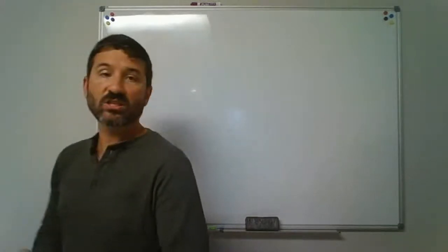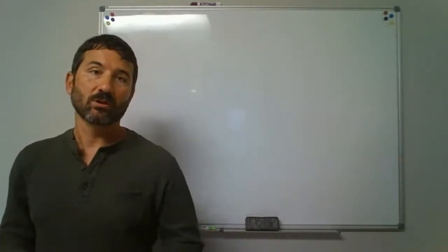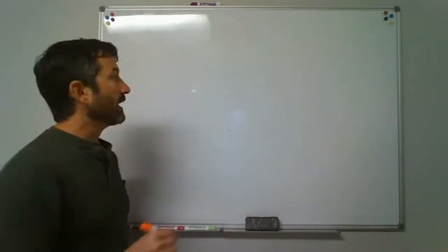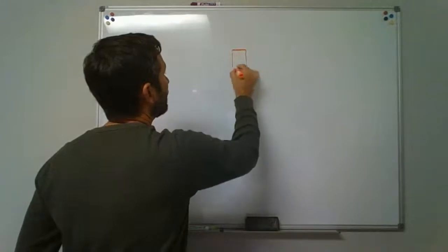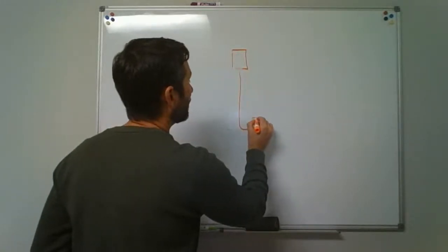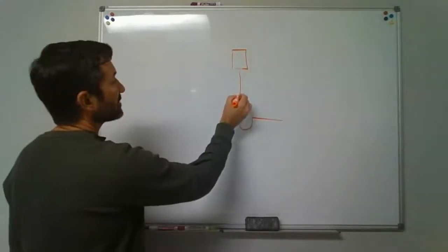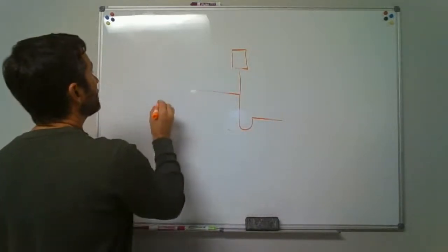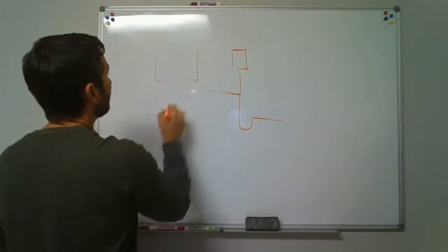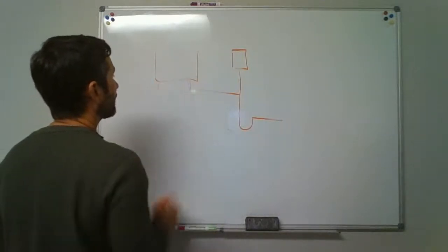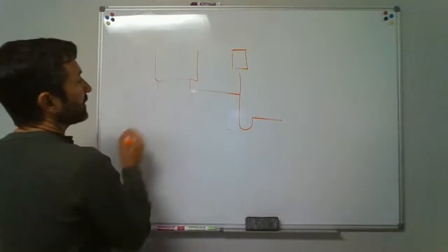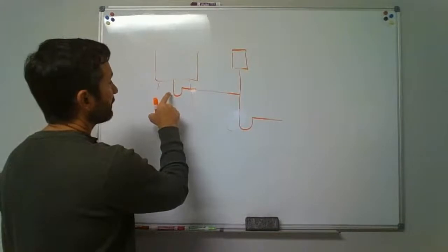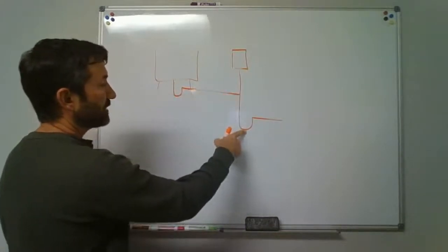Let's see what else. It also says we can't double trap something. Don't double trap it. Now, we did talk about in chapter 8 that you could take a washer standpipe and you could come into the standpipe and come out and connect for a laundry sink, okay? So if we did that and we have a sink sitting here, maybe it's even just one of those kind of freestanding sinks, and we plumb that, we're not supposed to come down and put a trap on that because then it's running from a trap into the standpipe, which is going into another trap.